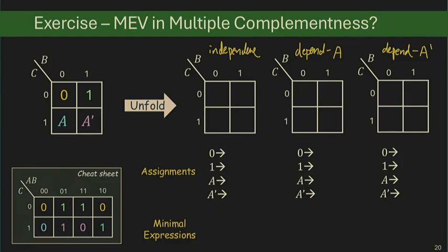Similarly over here, this means output is 1 when B is 0, C equals 1, and A equals 1. So when you see an A variable over here, that means B equals 0, C equals 1, output equals A. Or you can say B equals 0, C equals 1, A equals 1, output is 1. So A is just a condition.